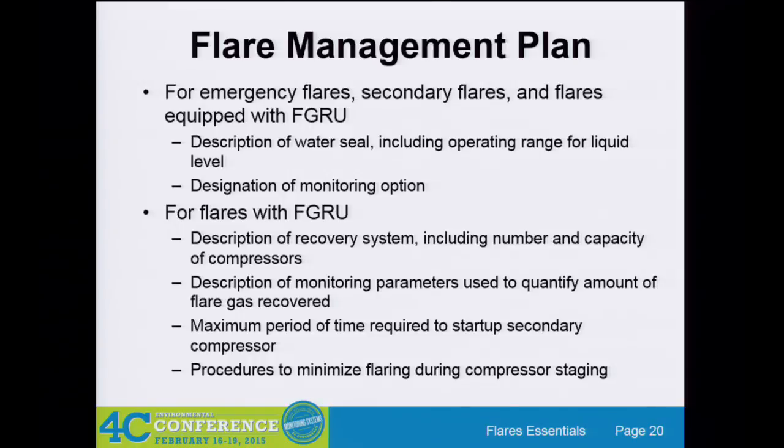Okay, for these flares that were all defined as having water seals, you're also going to need to give some detail on those water seals, so that you're going to document where that liquid range is supposed to be, how much back pressure you are putting on the system, and whether you are using one of the monitoring alternatives instead of the flow and the sulfur monitoring.